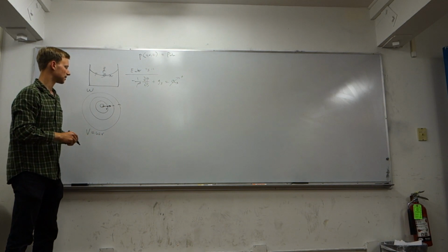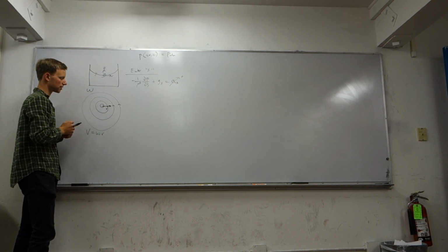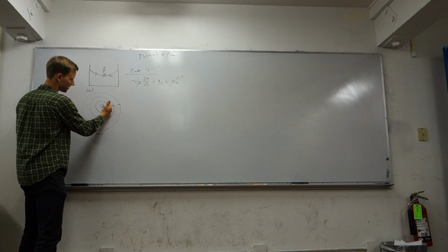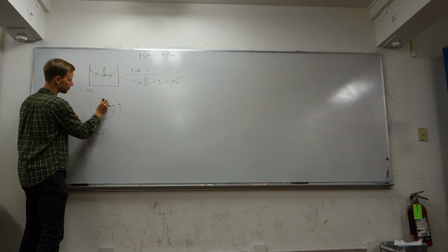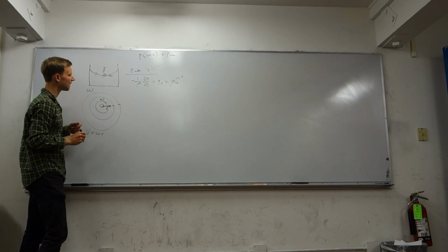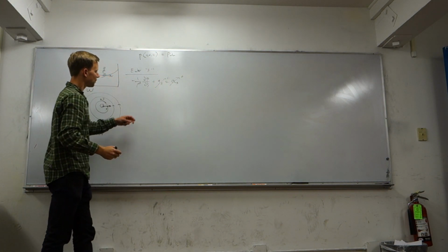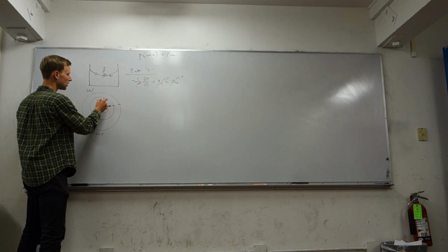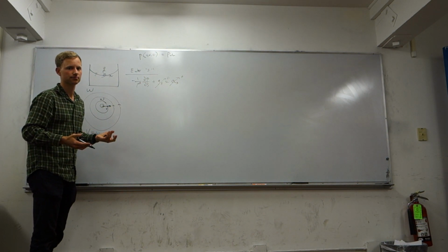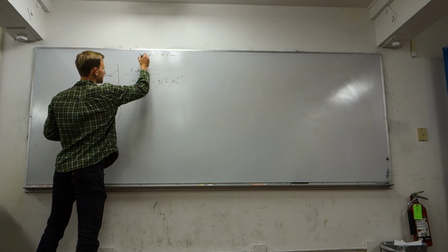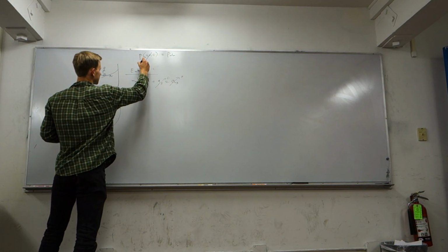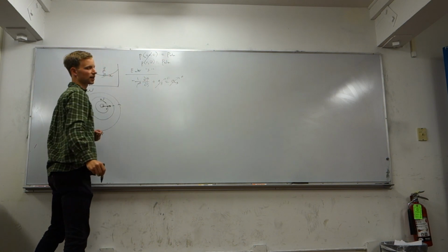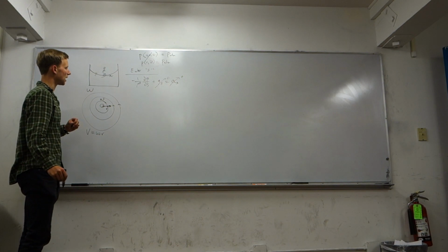The component of gravity that's acting along the streamline is also going to be 0, so the gravity vector dotted with the direction of the streamline, which we'll call s hat, goes to 0. That means that dp/ds equals 0, which means that pressure is no longer a function of our streamwise coordinate, which means that pressure will not be a function of theta. So we can take the theta dependence out of our pressure equation. So we're looking for P as a function of r and z equals P_atm. And this is obvious also if you look at it, but this is the more mathematical approach to why.